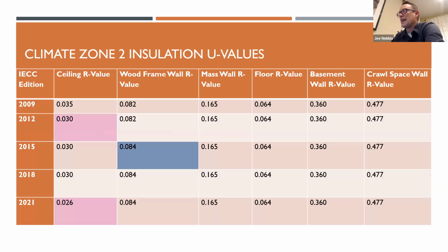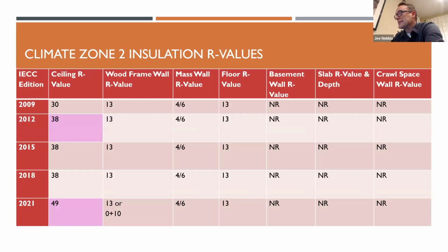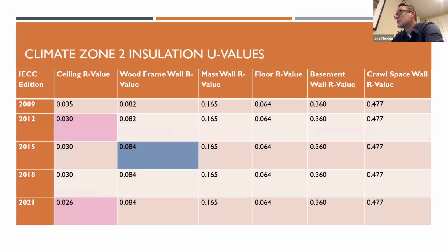They might not be that exact amount, but the point is you're going to have quite a lot more insulation than is required by code if you build with ICF in the South, or in most climate zones. Actually, you're going to have more. And that means you're going to have a major benefit on your UA, which means you may have some flexibility somewhere else in the envelope if you want it. So that's something to keep in mind.